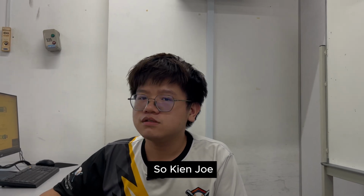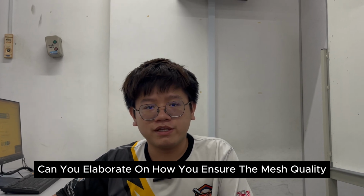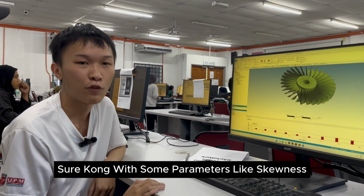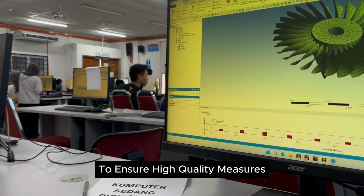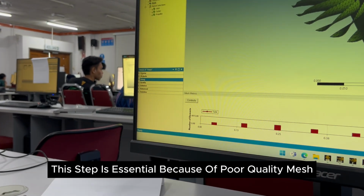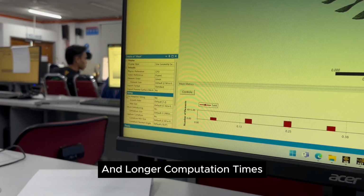I see. So Kenjo, can you elaborate on how you ensure the mesh quality is up to the mark? Sure, Kong, we tune parameters like skewness, aspect ratio, and orthogonality to ensure high-quality meshes. This step is essential because a poor quality mesh can lead to inaccurate results and longer computation times.